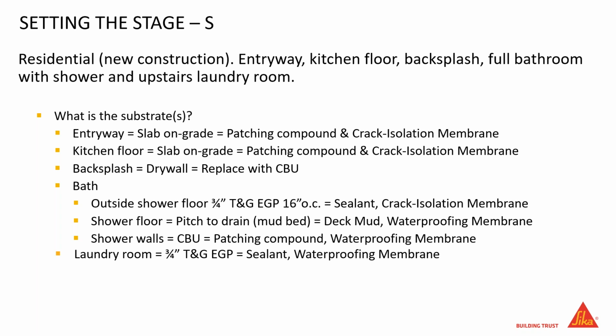Shower floor, we're going to pitch to drain. So we're going to use a deck mud and a waterproofing. Now that waterproofing can be liquid applied, it can be a sheet membrane, or whatever you're comfortable using out there. Again, we're a membrane company, so a liquid-applied waterproofing membrane would be our choice.